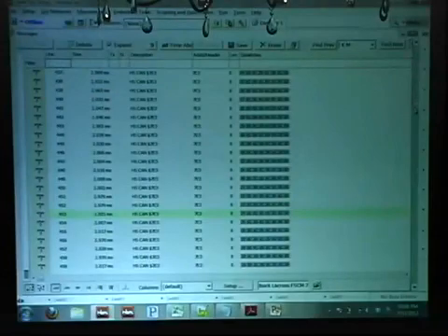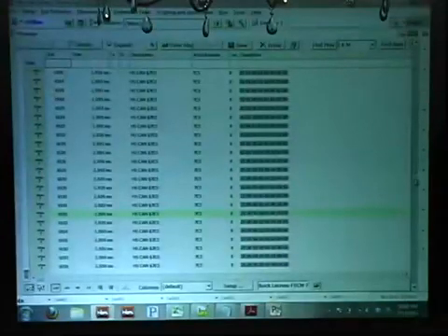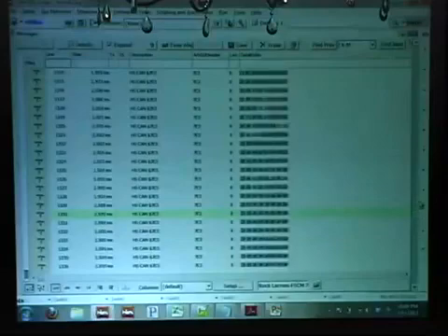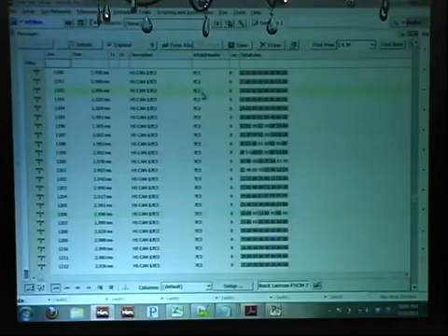If we look at this, this is actually a reflash event that occurred on my vehicle. I reflashed the transmission controller, or no, this is the fuel control module. Even when we're looking at this data, we can see we have a frame. This is what a frame is. It's an identifier and then 8 bytes of data. That's CAN bus. Identifier, up to 8 bytes of data. Could be less, could be more, but that's it. Really short, succinct messages that go out.